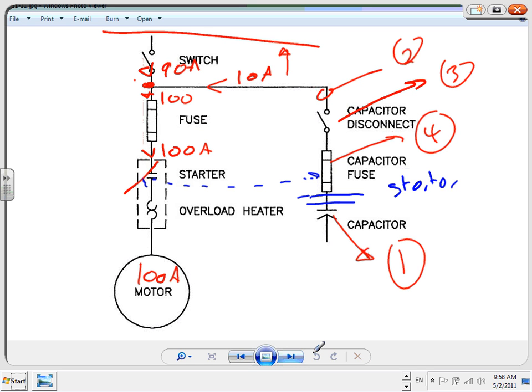Guys, just to give you an idea, I don't know if you've seen on these transmission lines, the utilities have capacitor banks. They go on and off. Every time they're looking at the voltage, they have a monitoring system. They're smart. Every time the voltage on the transmission line dips below, say, 10%, a sensor sends the signal to the contactor to close, and bring the capacitor up. So it raises the voltage. And when the voltage goes higher than a certain value, because the load went down, it opens up. So it's dynamic, electronically controlled capacitors.